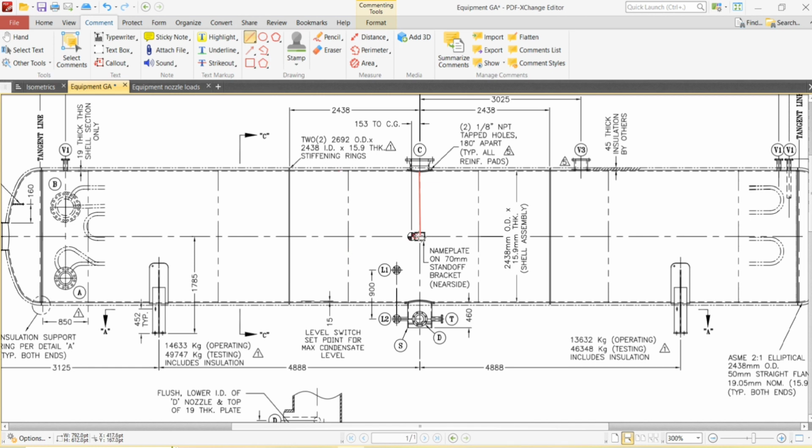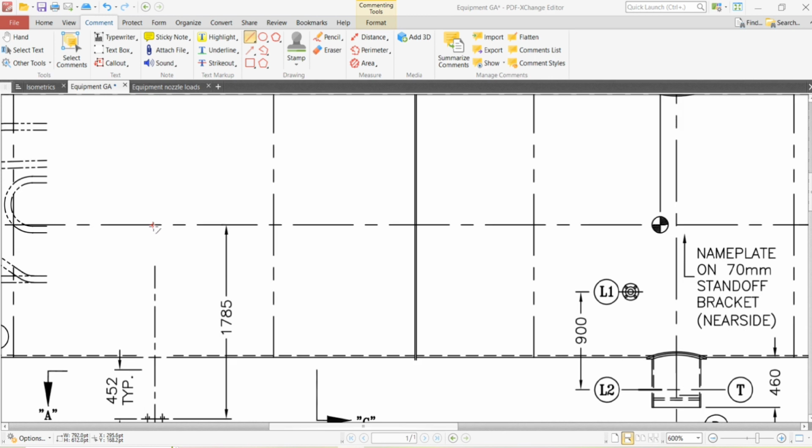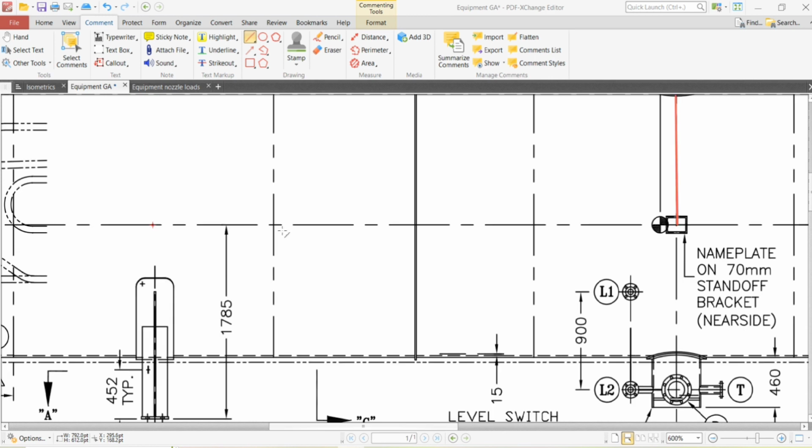Yeah, up to the center of the equipment we have modeled. Now we are going to model till the fixed point of the saddle. So you need to go towards the left and then again downwards till the outer edge of the equipment.